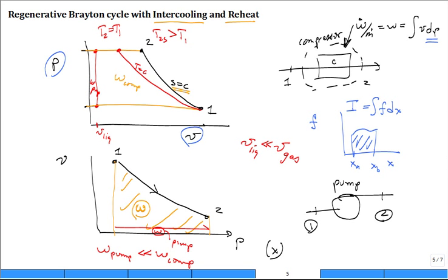But to have that device, usually a heat exchanger is a poor compressor, and a compressor is not a very good heat exchanger. So what they do is they say, let's do it in stages. We'll compress to this pressure level. We'll do it isentropically and then stop. Then we'll cool it back to the temperature of state 1, and then we'll compress it isentropically.